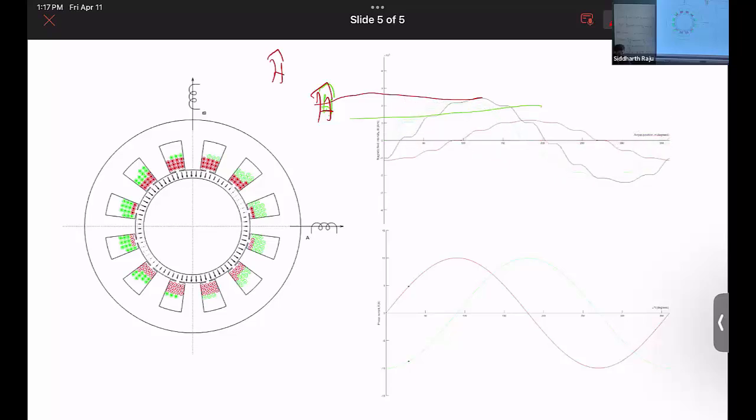What will be the peak of the H in the air gap? If I had a two-phase motor, 90-degree phase shifted, the peak H in the air gap was just H. If I had a three-phase motor, it was 3/2. For any polyphase motor, n, what will it come out to? Would it just be the number of phases divided by 2 times the peak of one of the waves?